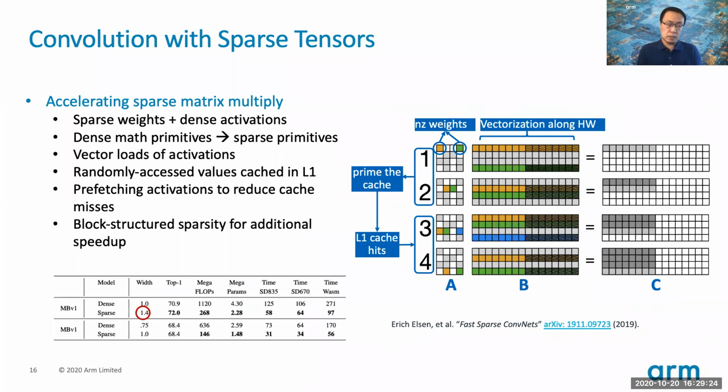So we've done a lot of work by this point to introduce high sparsity, but recall that one of the challenges is once you have the sparsity, how do we translate that to better performance? On the NPU, it is more straightforward because those hardware features will kick in once you have the sparsity, maybe the reduction of the compressed model size or the reduction in terms of the number of MACs. But here is an interesting example we see from the research community. It shows that even for the unstructured sparsity, it can still benefit the existing ARM IP, such as ARM CPU.